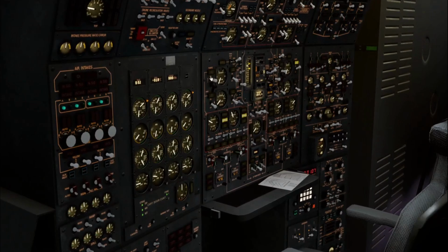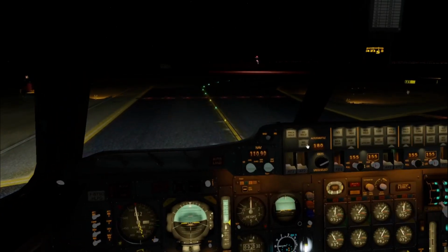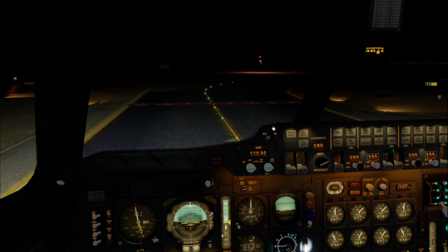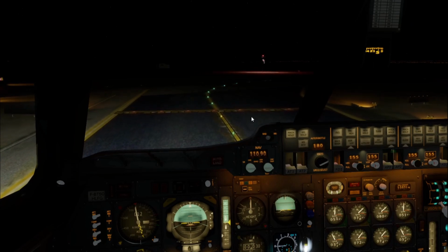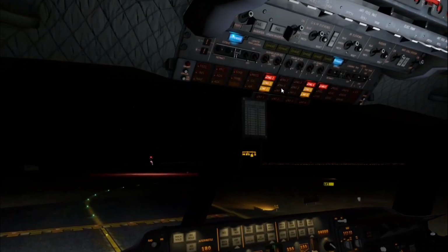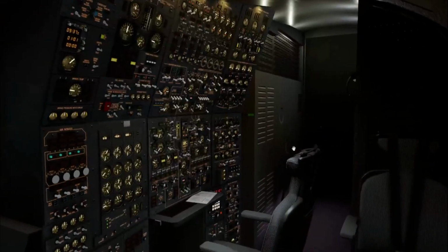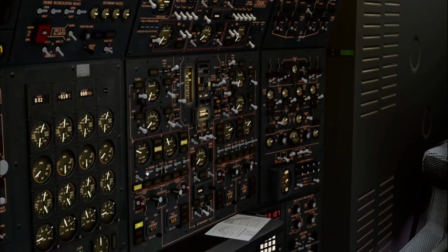There is plenty of fuel in the tanks. It shouldn't be, so we'll perform an extra transfer. And we'll put this to inhibit. We don't need these warnings. Yeah, this is disabled. We are not running these pumps.